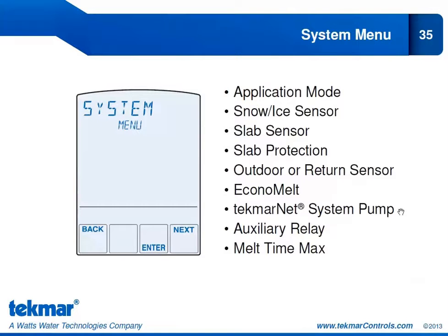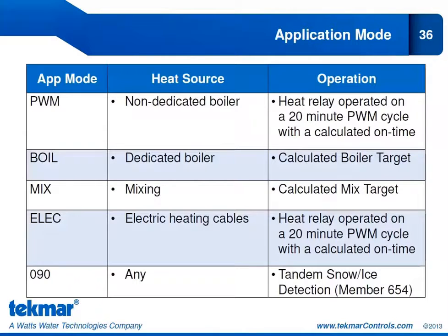You will also specify whether or not you need the TechMar system pump to operate during snowmelt. You will specify if your auxiliary relay is operating a system pump or if it is operating an alert device. And you can specify your melt time max.